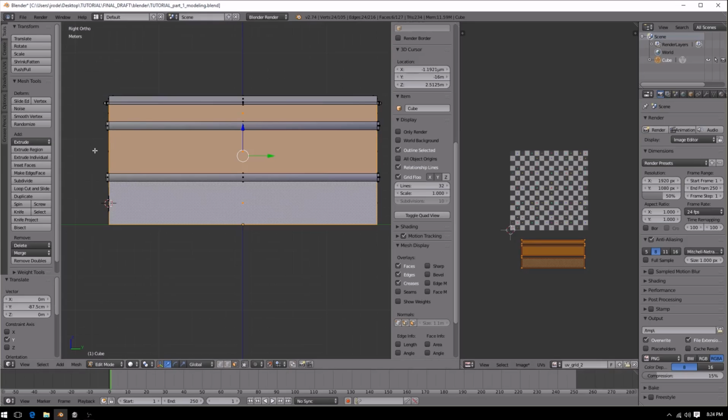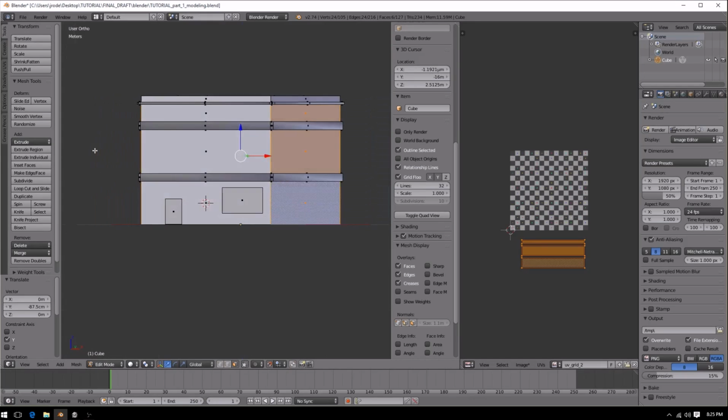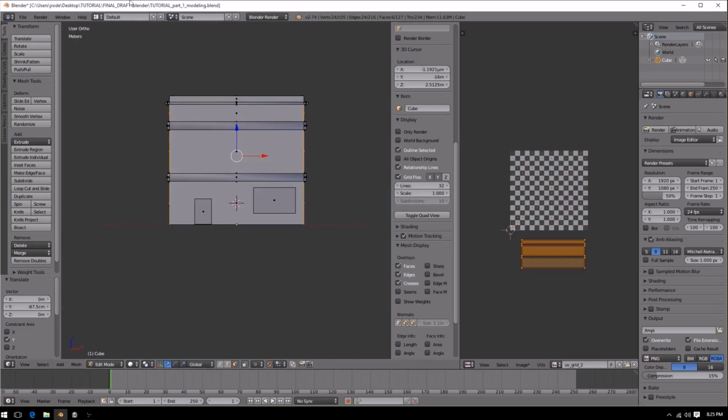So the next thing I'm going to do is use my camera pan views, the ones that are preset. I'm going to use the number 4 and pan in a perfect distance away. What this will do is not mess up the scale between the front and the sides of this unwrapping. If I actually move the camera now, the scale of this front might differ, and it's going to be a bigger pain to rescale this. So in order to keep the distance and everything kosher here, I'm going to use the camera pan views like 4, 6, 8, and 2 to move around the building until we're done unwrapping these pieces.